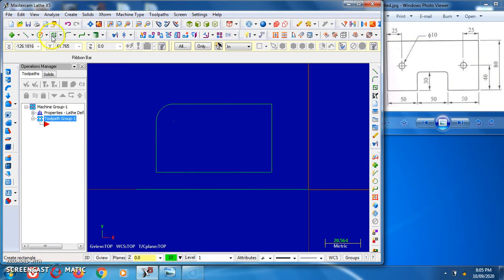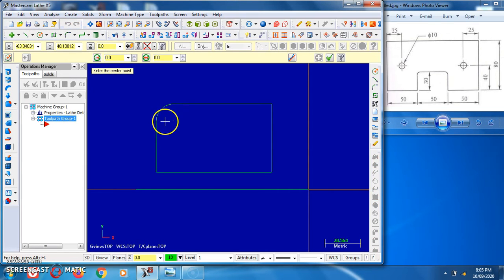So now in this way, with the help of any command we can draw the line, circle. Here we can draw the circle. Click on the circle. Suppose I want to create the circle here with respect to a point. Just put down the radius. Suppose I require a radius of 10 mm. Press enter. So we can prepare any type of object.